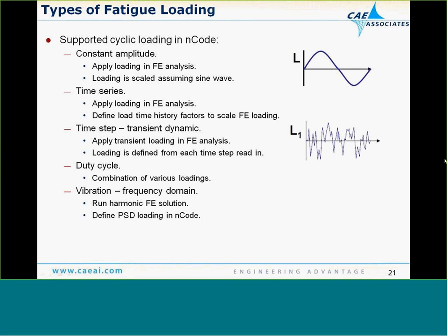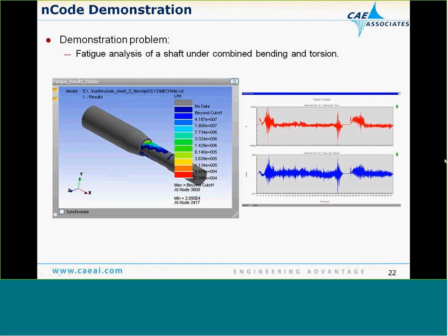And finally, if you want to do vibration fatigue, you can run a harmonic finite element solution, feed that into nCode, and then you would define your PSD loading in nCode. So at this point, that completes the brief overview. I'd like to perform a simple demonstration to illustrate the use of nCode in fatigue analysis.